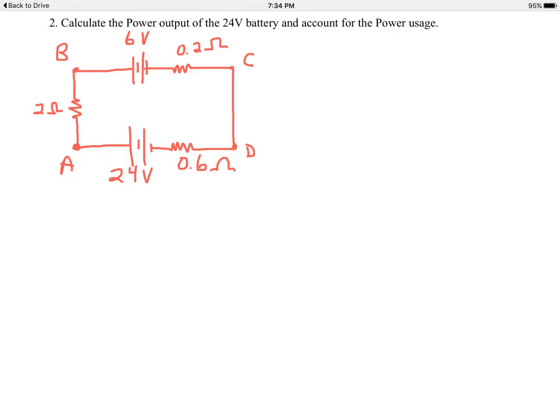Day 145, Part 2 of Kirchoff's laws, examples 2 and 3. Here we have a single loop with two batteries. Essentially what's going to happen here is the larger battery, the 24-volt battery, will be charging, in a sense, the 6-volt battery. The 24-volt battery is pushing current clockwise here, and the 6-volt battery, with the positive side pointing towards the left, let me label those, is trying to push current counterclockwise, but the stronger battery will win.